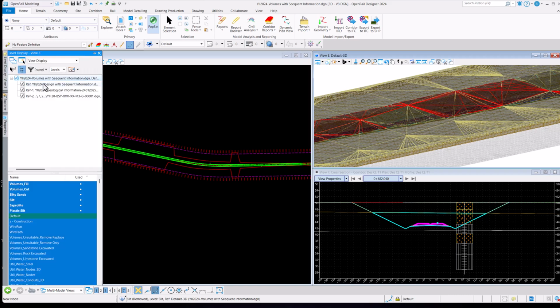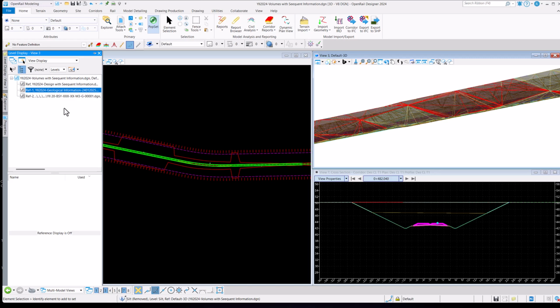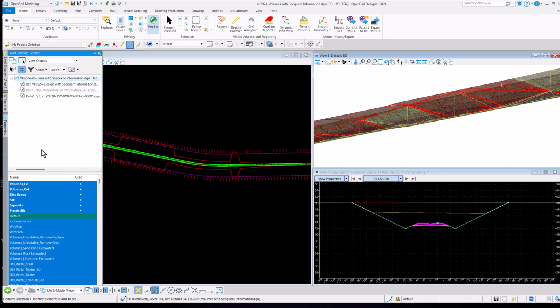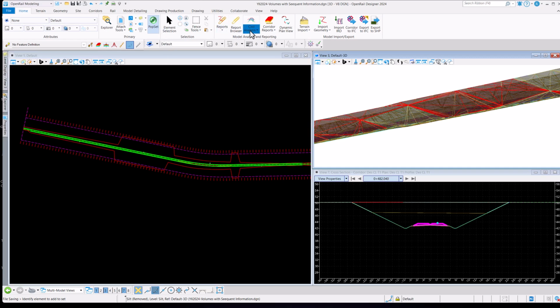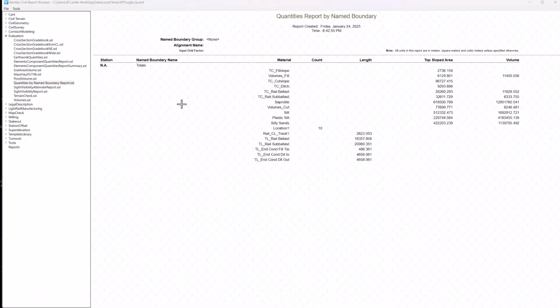So we have the quantities in the 3D model ready for BIM workflow to export to IFC to connect to the iTwin. Let me try to see a little more here. You can see all the meshes created in my 3D model. Easier to see on the cross section usually. But again, all is there. So now I can calculate the quantities, and you can see my report including all the quantities for each layer. And that's it.